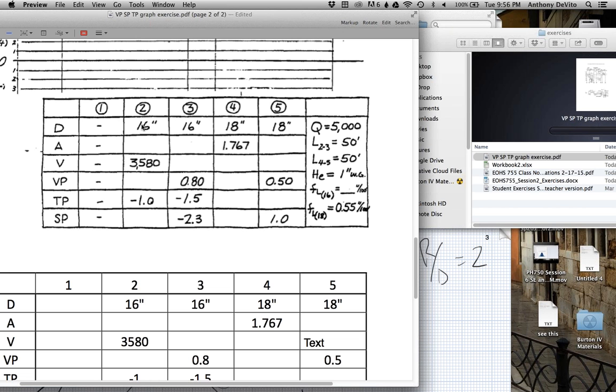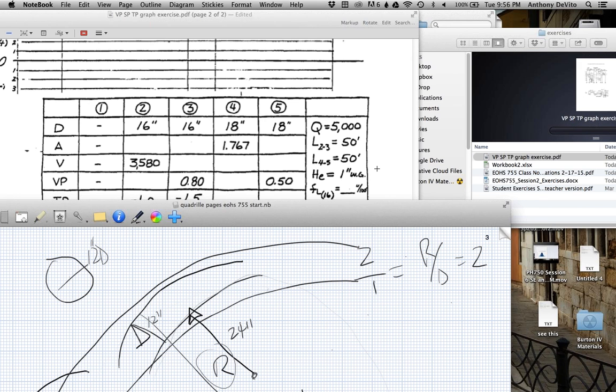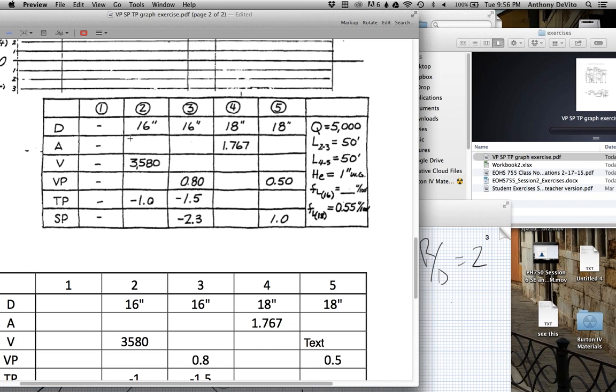On this side, the radius was 8 inches, which was 2/3 of a foot. So the area we would put in here is 3.14 times 0.67, which is 2/3, times 0.67 again, and that would give us the cross-sectional area here. I closed that file, but it wound up being a bit smaller, about 1.5 square feet or something like that.